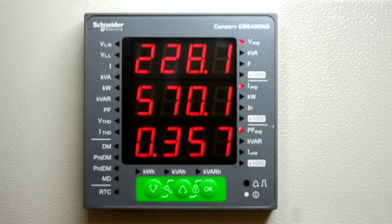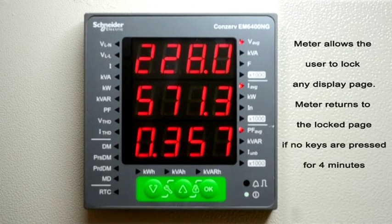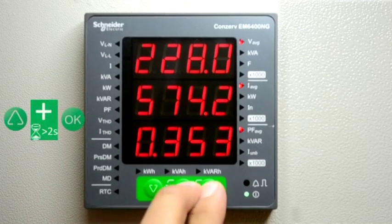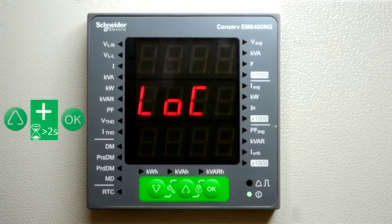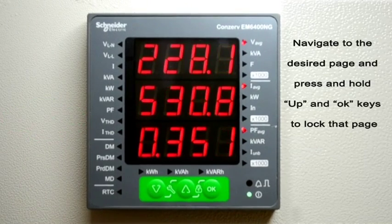One of the features of this meter is display page lock. For commonly viewed parameters, we can lock the page and the meter returns back to the locked page within 4 minutes after the pages are shuffled by the user. Also, once the page is locked, it is not possible to enter into setup and clear menu items. Press the up and OK key simultaneously for 2 seconds to lock or unlock the page.